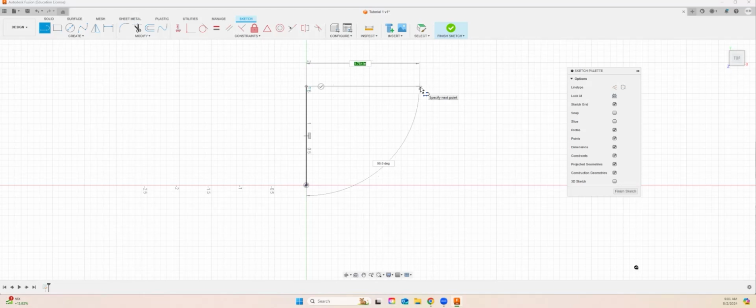let's say this will be 3 inches. So you see if I type 3, I press enter. I don't have to type inches because we already know what it is. You can type millimeters and you can see it automatically transforms into what 3 millimeters is. But if I go back to 3 inches or just three, the program already knows the unit. So I'll press 3. You can see it's also making a 90-degree line with the previous one. Press enter, and there we go.